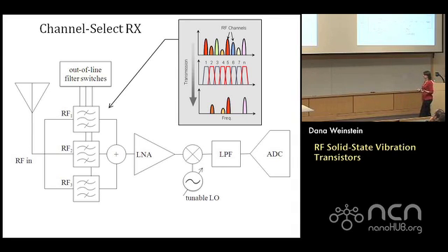So once I get this technology platform for millimeter wave ICs with high quality factor resonators, I can think not only about frequency sources, but about filters. And using gallium nitride, I can actually, and I'll talk about this in a moment, configure those filters, turn them on and off, which is not possible with any other piezoelectric material out there. And I can think about channelized radio architectures that switch between filters, allowing us to configure front-end radios very easily, right? There's a big program, a big effort here.